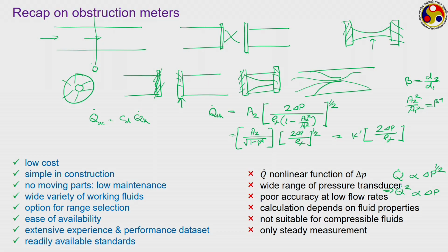And they are generally used only for steady measurement. We hardly use venturimeters etc. for transient measurement, because again the application of Bernoulli's equation is generally more common in steady flow situations.